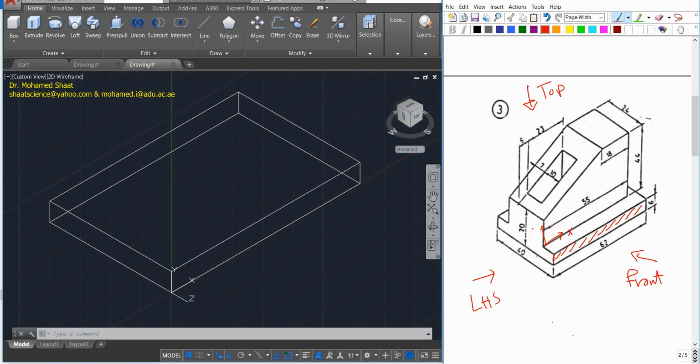But as I mentioned before, because AutoCAD has some problems with creating these faces, we can simply create this face directly over this front face. Then I'm going to move it back with this distance. But how much is this distance? You can do some simple calculations here: 40 minus 24, divided by 2, gives us 8. So this depth here should be 8, and there should be another 8 on the other side, right? And this is what I'm going to do.